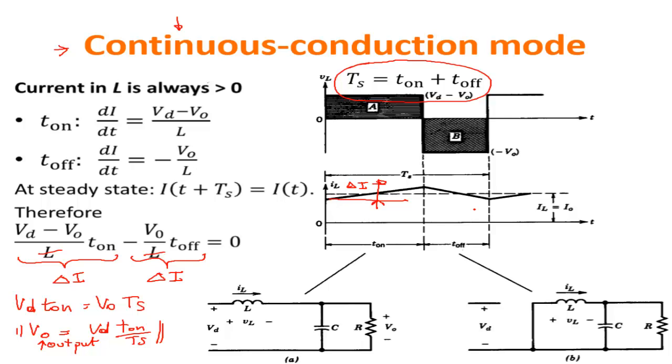This is a requirement, because the current in this T off time goes through the diode, and the diode can only conduct a positive current. But of course things can change. If the average current absorbed by the load is reduced, then this starts to move down, and you could obtain that this point goes below 0. And this is a situation that we must check.